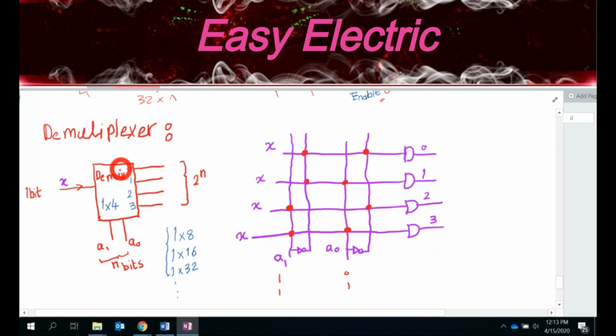So similar with the decoder, encoder, multiplexer, we actually have an enable pin. So I add one enable pin here. I call this enable. Usually you put one bar, which means this dot that you see. It tells that this pin is active with the 0. That's the meaning. That's the reason why I put this bar on the enable, and also I have this dot here. It says it's active whenever that is 0.